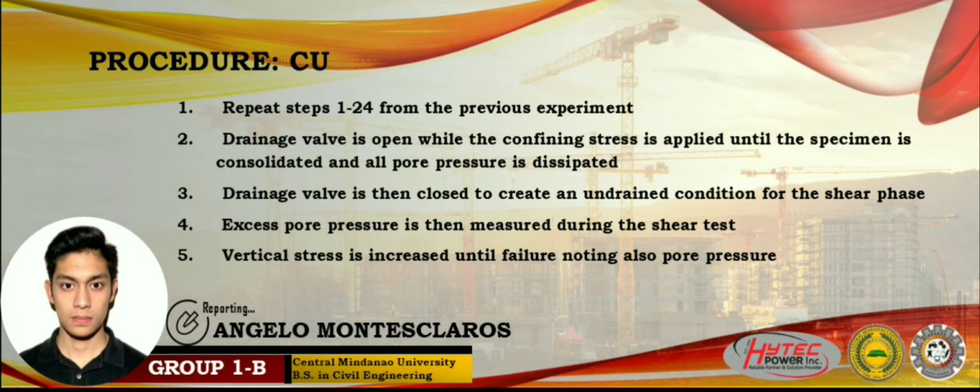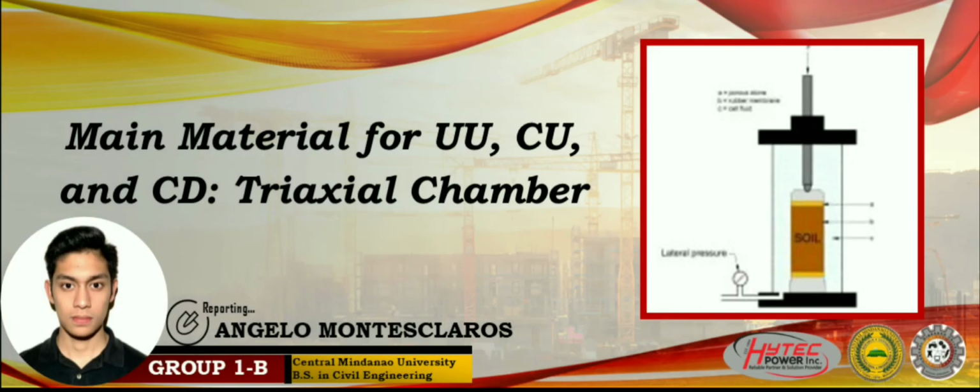But it is closed during the shear phase to create an undrained condition. Then the excess pore pressure is measured during the shear test. Vertical stress is increased until failure, noting also the pore pressure. The main equipment for UU, CU, and CD tests is the triaxial chamber.